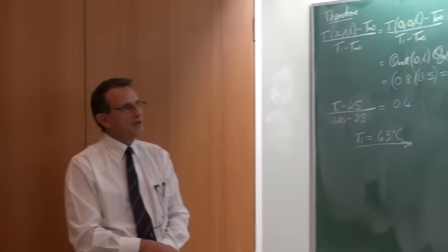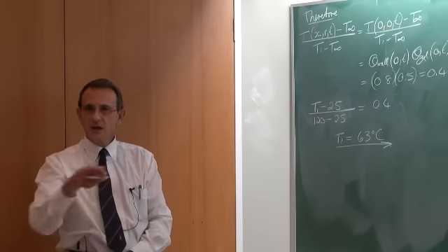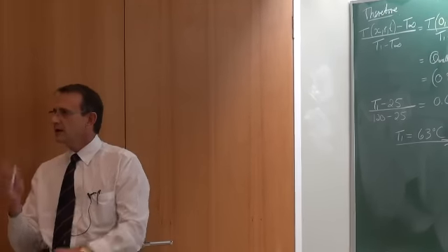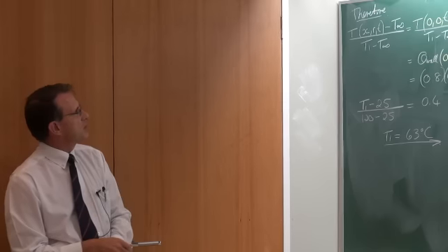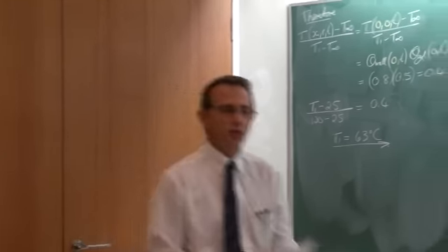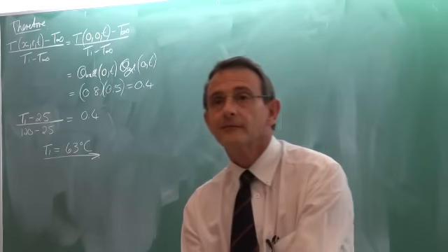63 degrees Celsius, so it is the intersection of the plane wall at its center line multiplied by the cylinder on its center line to give us the temperature at point 1. Any questions before we move to point 2? Okay.